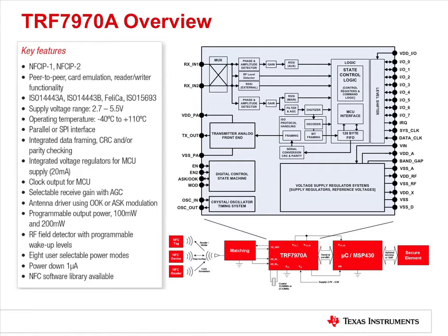The devices also offer unparalleled flexibility via the various direct communication modes on the device to allow implementation of custom protocols as well as other 13.56 MHz standards. The receiver system enables AM and PM demodulation using a dual input architecture to maximize communication robustness. The device also has a very low power RF field detector with programmable wake-up levels to detect if an RF field is present and another NFC device wants to communicate with it.